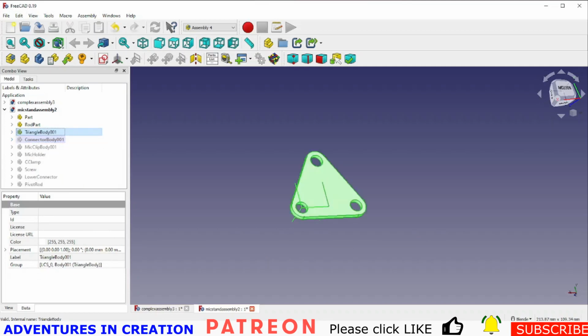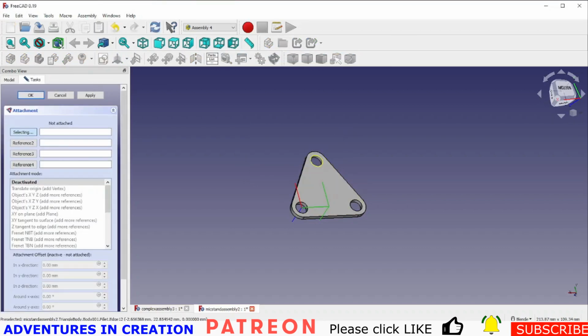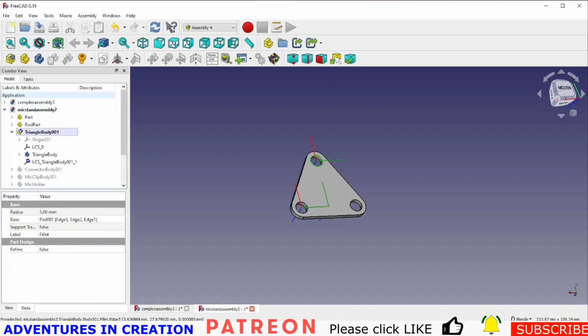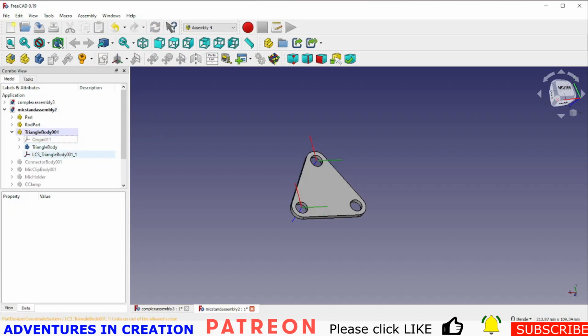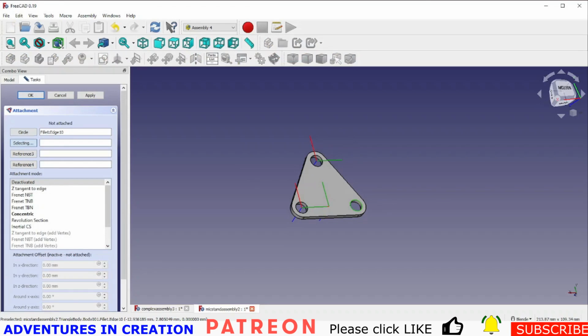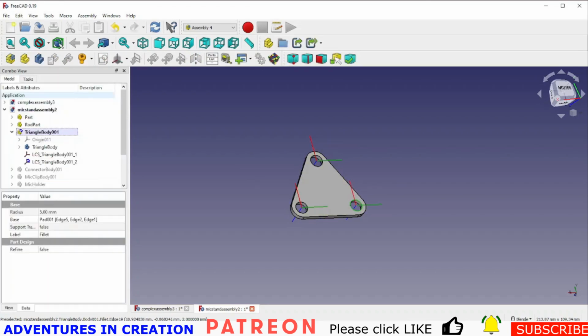The next one's actually the triangle part. Do the same thing for that. So I'm going to select it. Here we go. I said I wasn't going to show you all these, but I'll show you one more. Concentric, apply, okay. And looks like I already had one on this one as well because I've been messing with it. So I'm going to get rid of that. And then I'm going to select here, okay, and concentric, apply, say okay. And I still have a third one. I don't know where that came from.